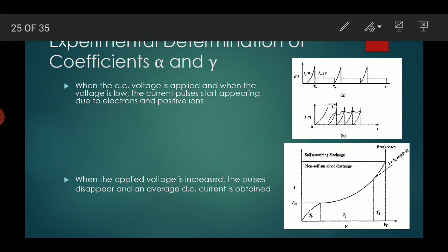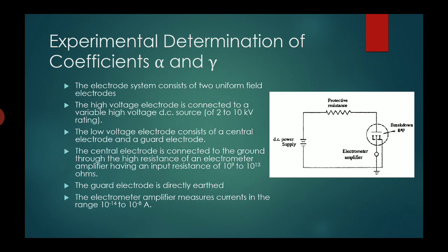So we are talking about this circular container, that is the ionization chamber, which is either a metal chamber of chromium plated mild steel or stainless steel, or even a glass chamber, depending on the pressure the chamber can withstand. The electrodes are usually made of brass or stainless steel, because both are corrosion resistant as well as good conductors of heat.